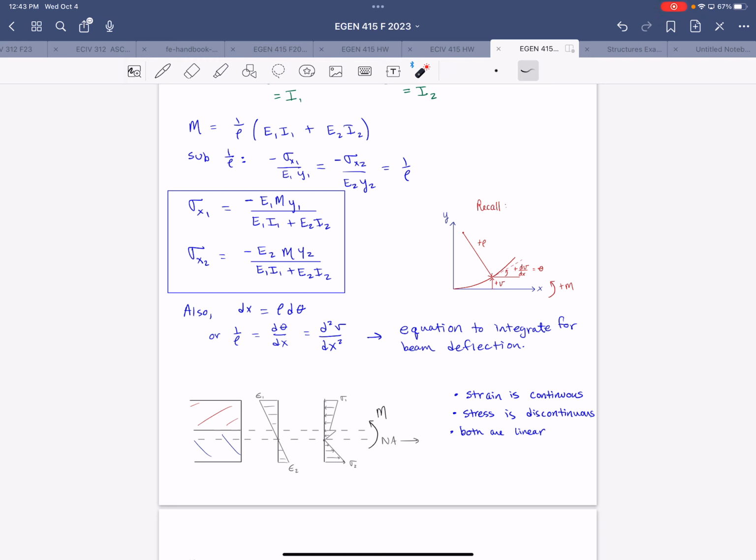Sure, yeah. If you have a really, really deep beam, then it's a different approach to tackling the shear and moment. It's more of a Timoshenko type. I don't know if you've heard that in other classes, but it's usually not something that's covered much in undergraduate courses. But it would be a different approach to sorting all that out.